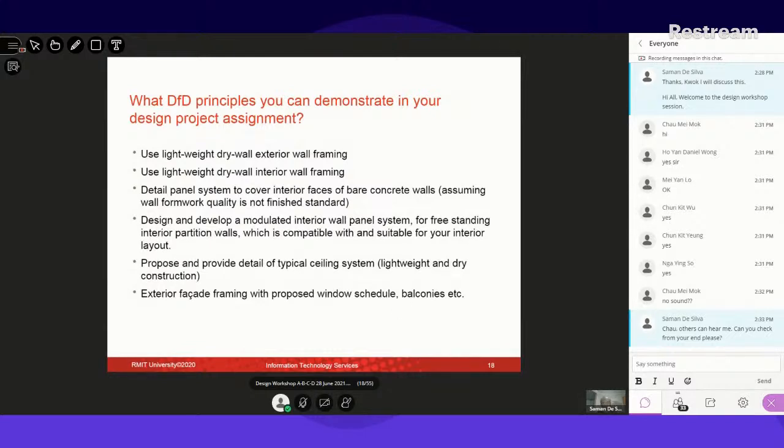if you look at the traditional buildings a few years back, most of these partition walls were made out of either brickwork or blockwork. It is wet construction, and there are two disadvantages I can see in that one. Sometimes non-load bearing walls are done like that. I can understand load bearing walls being like that, but partition walls don't have to be.